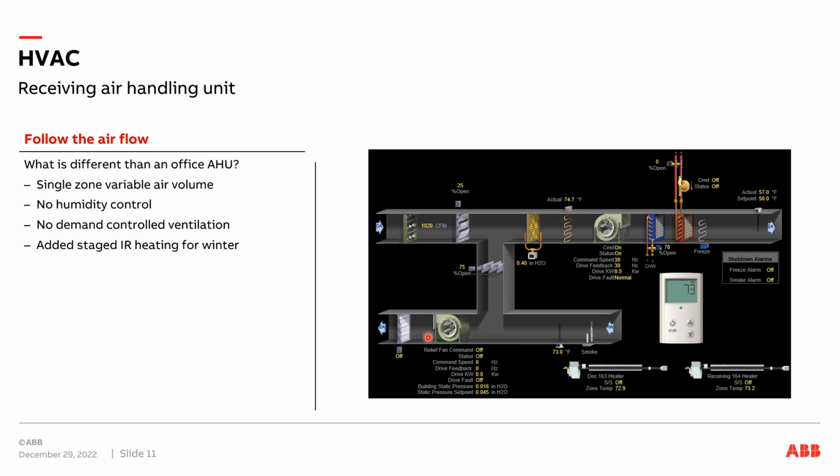So I talked about wanting to keep things positive so we don't bring in too much outside air leaking in. We don't want doors getting propped open because we're exhausting so much air through our front door that the door won't latch shut. So what we can do is first open up these dampers here and let air naturally leak out. And then if the pressure is still too high, you can turn these relief fans on and help blow air out of the building.